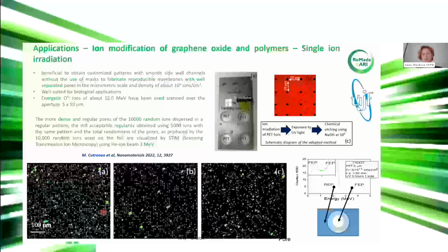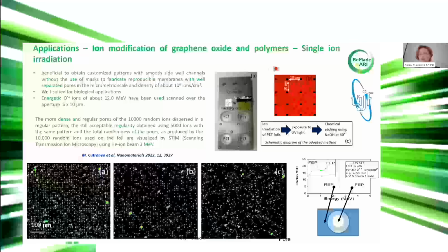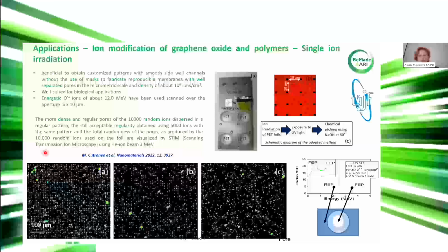In this case, we used a procedure where we were not broadly steering the beam, but directed the beam to this position, this position, this position, with a very small amount of ions, to ensure that statistically each position is hit by at most 3 ions, in the lowest case 1 ion: 1, 2, or 3 ions.